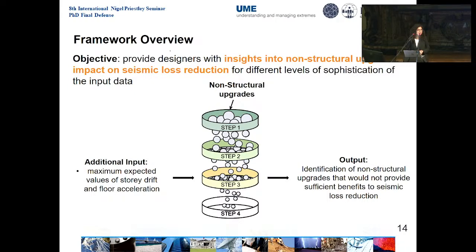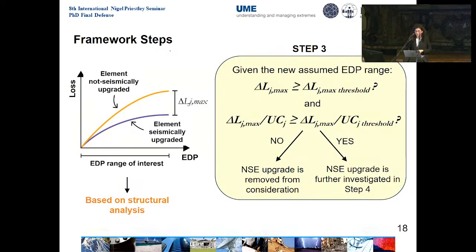I have just a quick question, but I think you already answered it while answering Flavia. I was going to ask, the database of component EDP to loss curves, where does it come from? Because you show the framework, but you never say exactly where the data you used comes from. Yes, basically we take the fragility and consequence functions from FEMA P58, and we are upgrading some of them based on more recent research work, the one published by Steneker in 2022. So some of the fragilities have been modified to account for updates, but the basic database is the one of FEMA P58. Thank you.